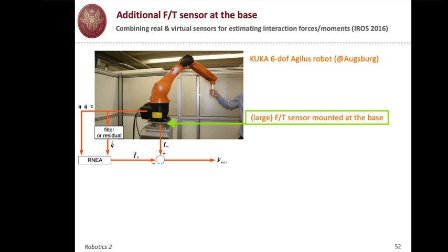If you push the robot before the force-torque sensor, nothing happens. So with this simple observation, if you move the force-torque sensor really to the base, then everything else will be beyond it, although it will not be a single rigid body, but an articulated body. Okay.